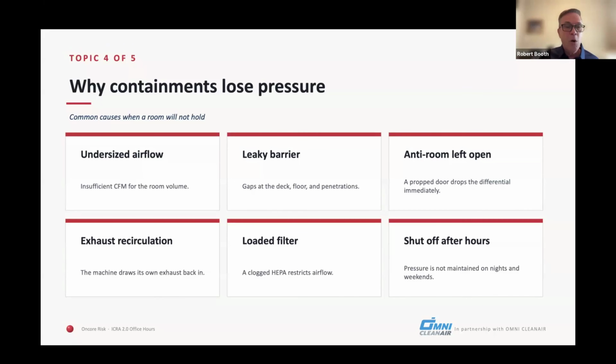So there's no guideline, but my guideline is anything that affects other areas, and that's generally about an inch of negative air pressure. I don't know what your thoughts are, Josh. In our isolation rooms, the reason we put those pressurization limits in our pharmacies is because if you draw too much negative air from another space into an area, you're going to affect that space.